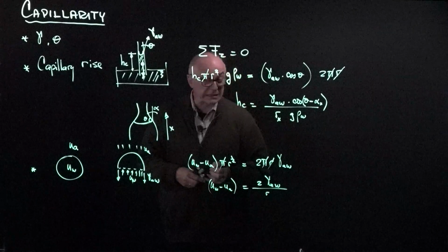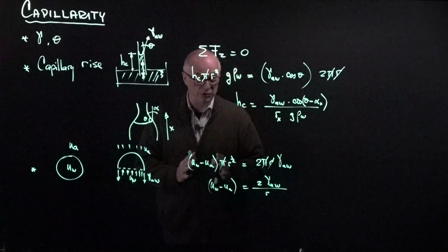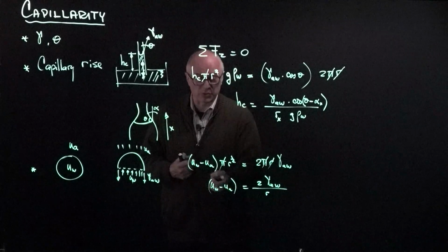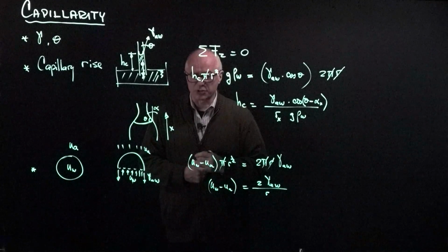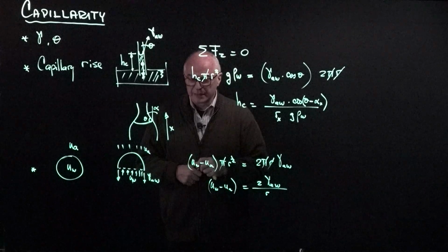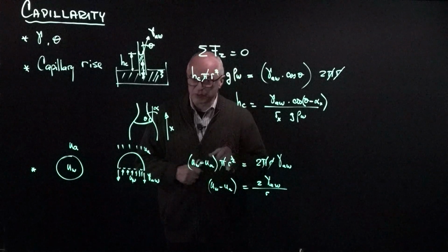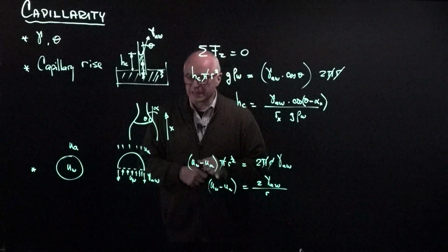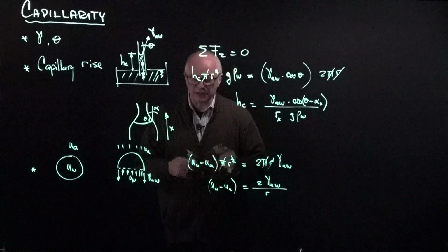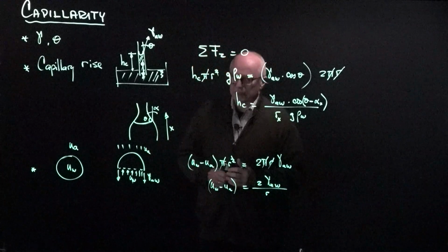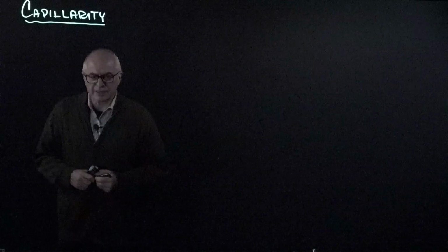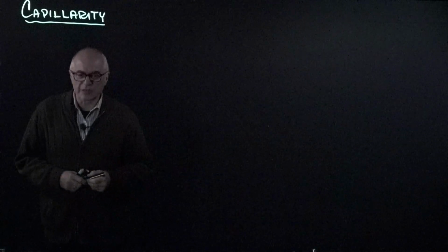Once again, this is telling us that the smaller the pores, the larger the difference between the water and the air pressure. Now, in this case, the water is under compression. As we will soon see in our soils, the water will typically be under tension, and we will see why. So let's explore the next phase of this exercise. The story gets incrementally more interesting.